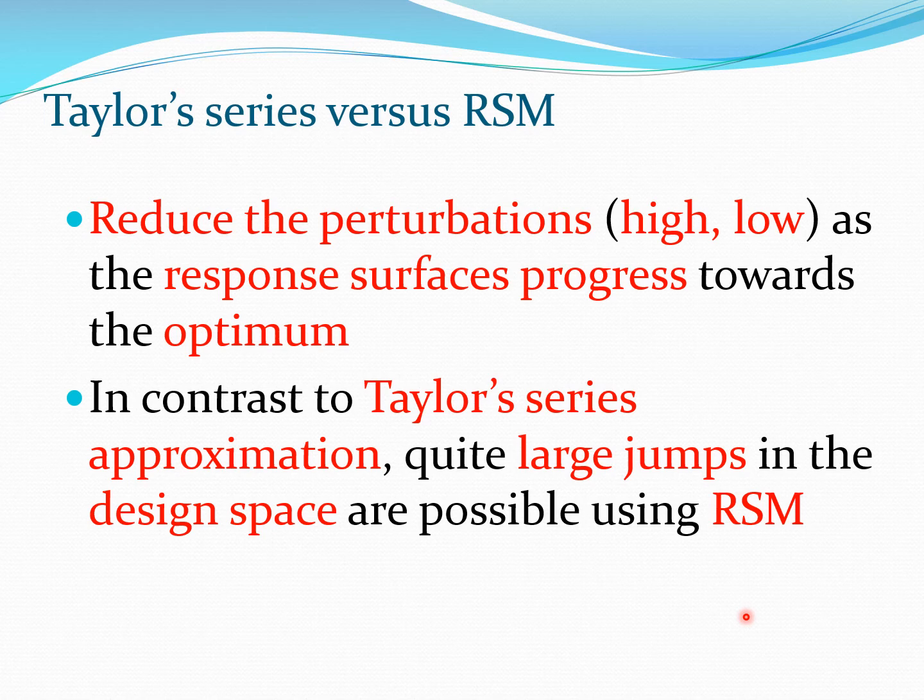Now, some people say there is a similarity between Taylor series and response surface method, and conceptually it may seem like that, but Taylor series approximation is valid very locally because it uses derivatives at a given point. Whereas one can think of response surfaces as very rough kind of Taylor series systems. You are taking large jumps in the design space by doing curve fits. So in some ways there is of course a relationship between a curve fit and the Taylor series in a certain limit type of way, but these are quite different. But you could think of taking very rough Taylor series and also doing response surfaces.